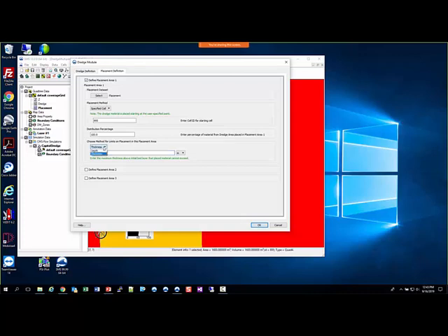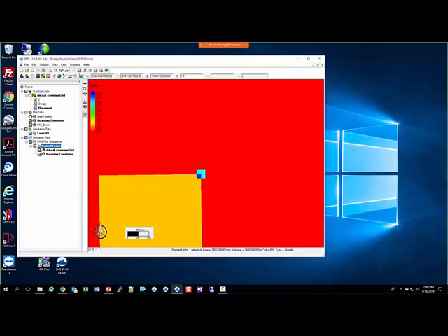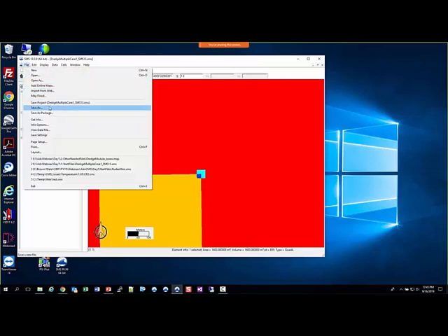You could base it on depth if you want, but then you'd have to know how far down from the surface of the water it is, things like that. So we're just going to say we want a thickness of 1.1 meters on that bottom for that placement, and that's it. If you have other areas, you can do the same thing for each one of those, but in our case, we just have the one. Make sure you click OK. And of course, as we mentioned earlier, you might want to save regularly. So you can file, save your project into another location.